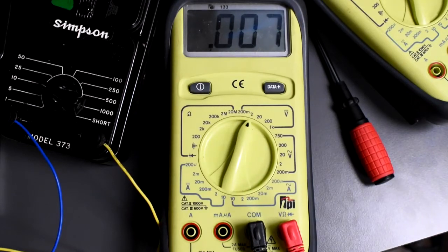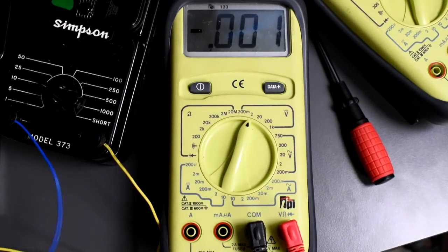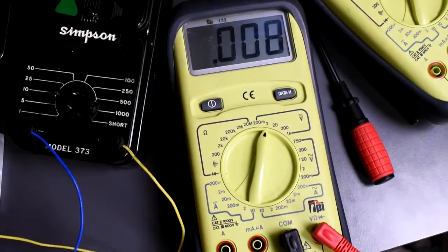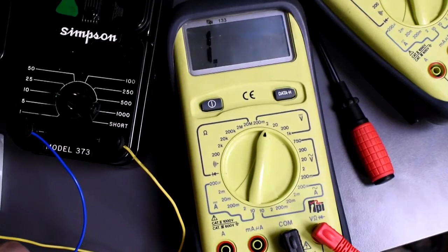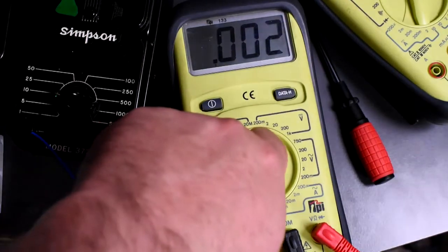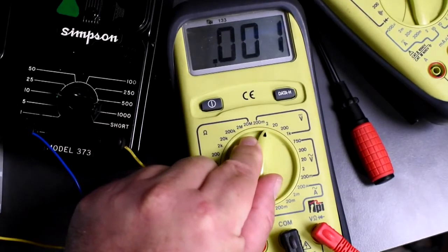Let's see what this meter does. I'm going to take these probes and put them right across the power supply here. Okay. What do we get? Voltage here. All right, we get something like this. You see that 1 and a dot? That means we're out of range in this particular meter. In some of the meters, you're going to see OL, like over limit or overload or something like that. Now, okay, so we are measuring 5 volts. So we're going to go to the next one.